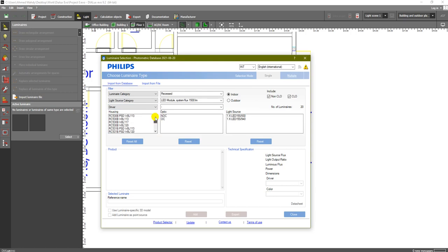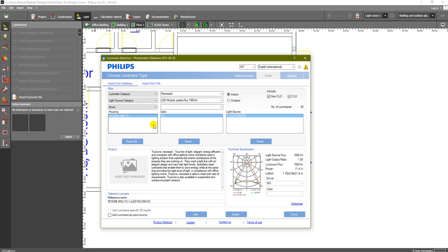Whatever the type, you can see here the optic representing the diffuser, the shape of the diffuser. So as an example, I will choose this one and this one, for example. This is the code. Each one of these has its own type. When I selected a random one of these, you can see LED 15S. What does this mean? 15 and add 2 zeros gives us the lumens. So 15 means 1500 lumens. As you can see, 1500 lumens.